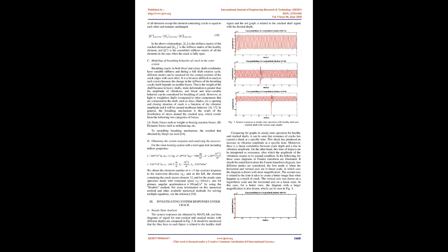In this regard, M is the mass matrix of the rotor system, G is the gyroscopic matrix, K is the stiffness matrix, Q is the force vector, and q is the displacement vector of the whole system in the general coordinates, as well as Ω is the angular speed of the system. The matrix coefficients of the equation of motion of the rotor system can be introduced as the following equations.